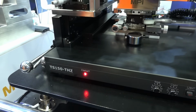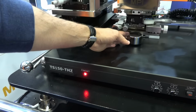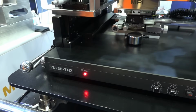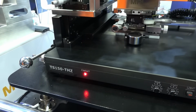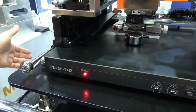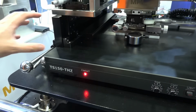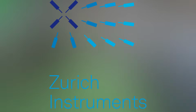So for example, if you have landed the probes or you have a contact, you cannot move the chuck anymore. Even though everything is mechanical, it's locked in place, so you can't accidentally scratch all your probes and everything across your wafer. You also have this contact support which allows you to lift just enough so that everything is in focus, but then if you raise and lower this very quickly, it wouldn't matter how fast you touch this. It will always land the probe at the same rate through the mechanical dampening systems that are built into it. So even though it's fully manual, it has a lot of the features that automatic probe stations would normally have.